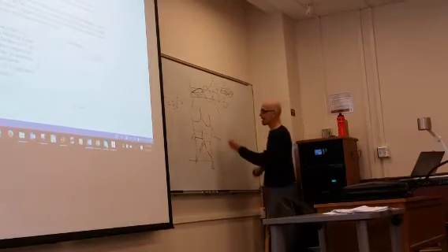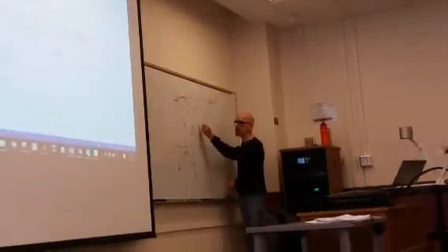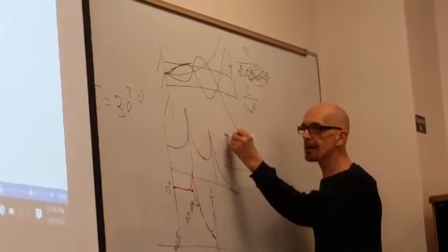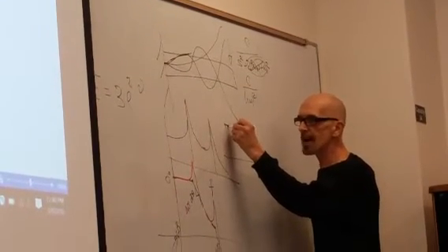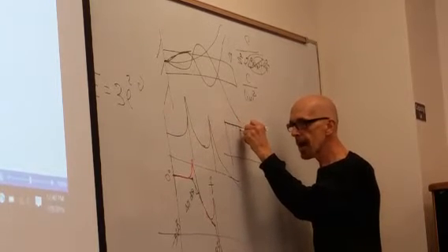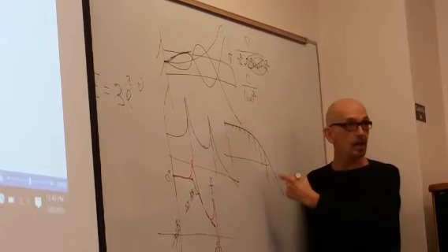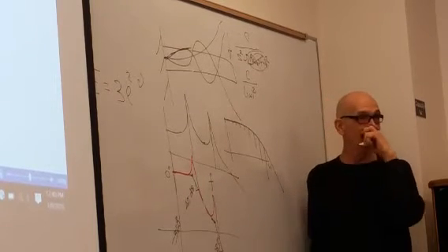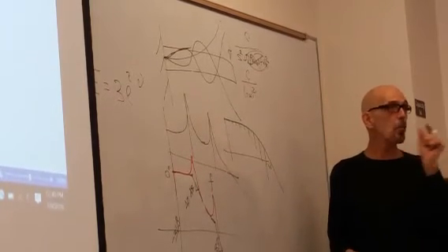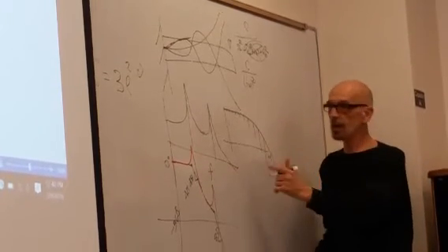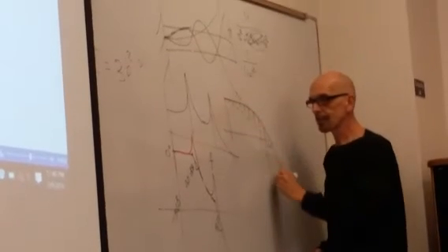If the phase is like this originally without a time delay, and you start subtracting omega times 0.1, well, at low omegas, you're not subtracting anything. But at higher omegas, you're subtracting a lot, because the phase is omega times 0.1. So when omega gets huge, phase gets huge. So the phase drops.